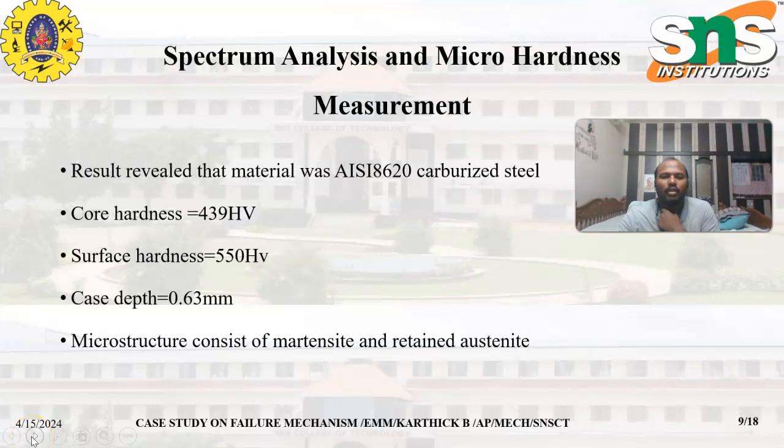In spectrum analysis and micro hardness, it is revealed that it is an AISI 8620 carburized steel. And the core hardness of 439 HV, the HV is nothing but Vickers hardness, and the surface hardness of 550 HV, and the case depth is 0.63 millimeter.